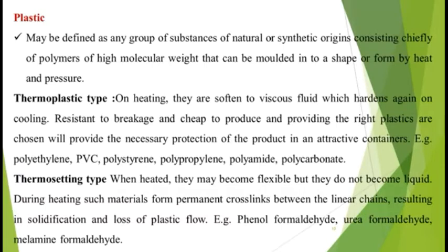And the linings are epoxy linings, vinyl with aluminium tubes, and also phenolics. The phenolics are effective with acid products, and epoxides with alkaline materials, and also wax is used for tin tubes, and it does not have the suck back property.